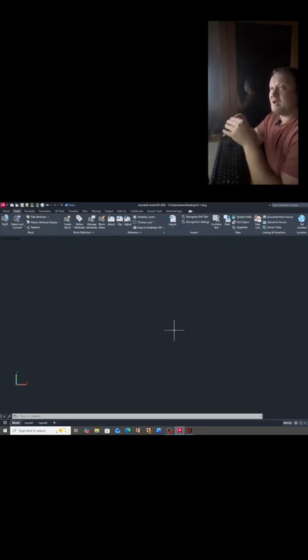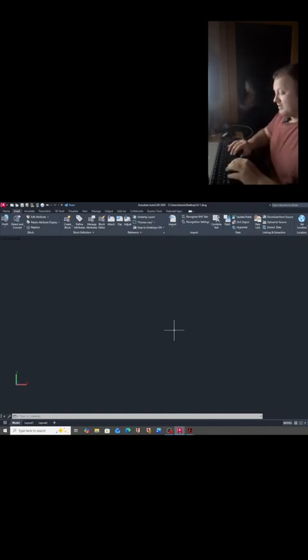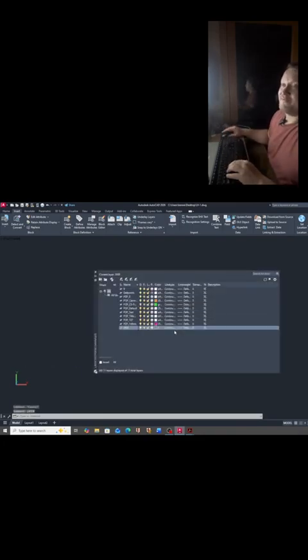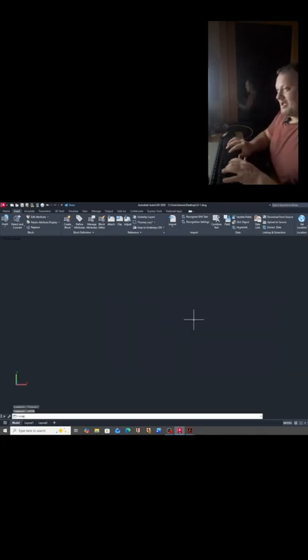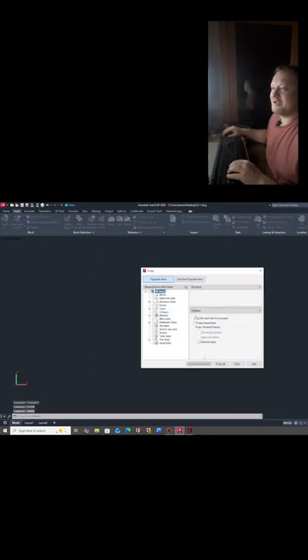I'm going to make a sticker that's going to be named wall, and that would go on a blue colored pencil. And now every line I draw while that is turned on would fall under that wall category with the blue pencil. So type in layer, and that may not have been a great way to describe that, you guys, but I'm trying to think of the best way to explain it.